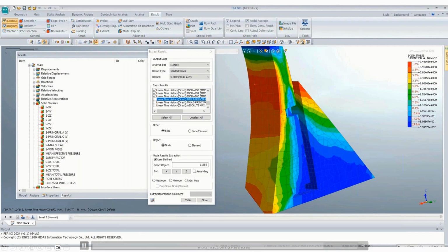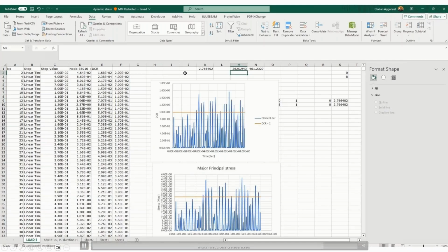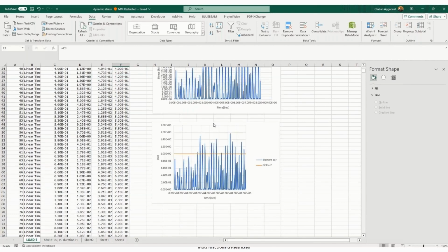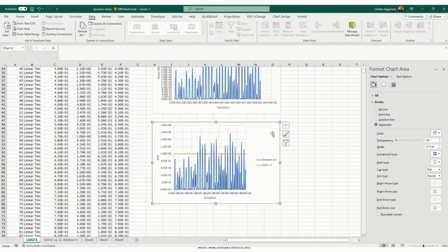Anyway, we are running out of time. Suppose, let us assume this is DB, then this DCR criterion is not fulfilled, that means tensile stress exceeds the allowable limits. For DB condition, it should not exceed that. For MC, it may exceed, then we have to find out the cumulative inelastic duration. But let's say this is MC. So we have plotted the DCR. So let's plot the cumulative inelastic duration. So what to do for that?